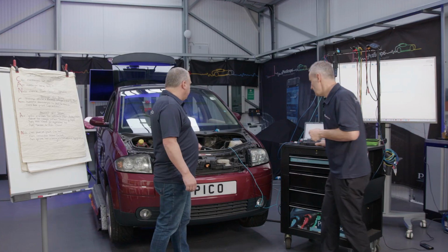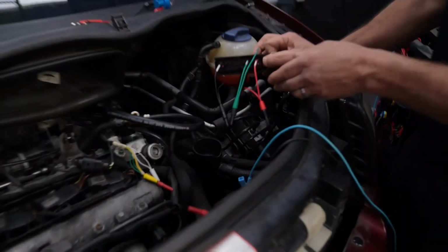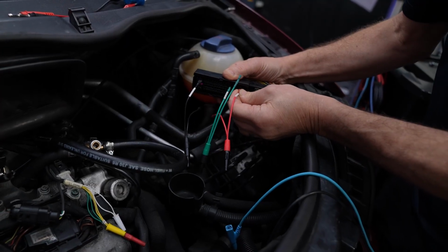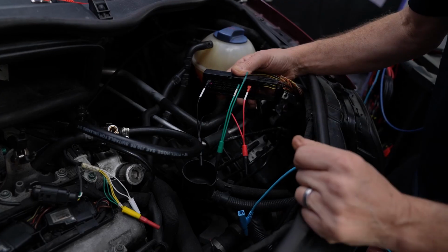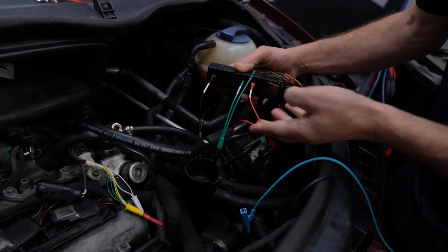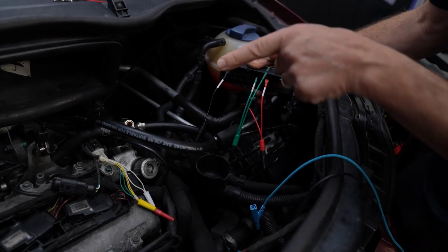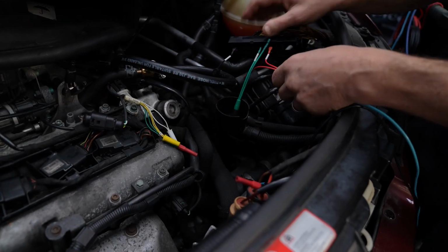So Ben, if you want to just come in and have a look here. We're using the breakout leads on the ABS connector. Always have a look at the drag, we call pin drag test, to make sure that these pins haven't opened out. These are the correct sizes for these terminals. So here we have our permanent feed. That was the ECU earth, which we have checked with the milliohm meter. Nevertheless, we'll load it. This one is ignition.